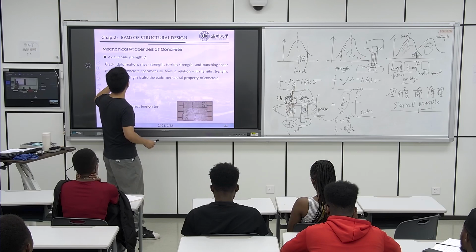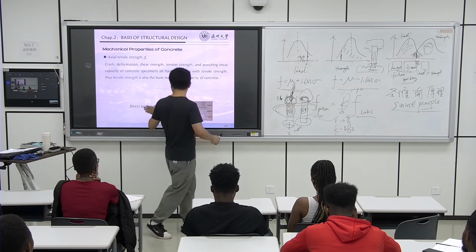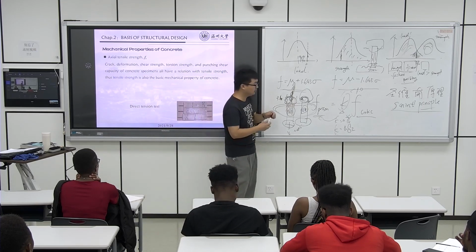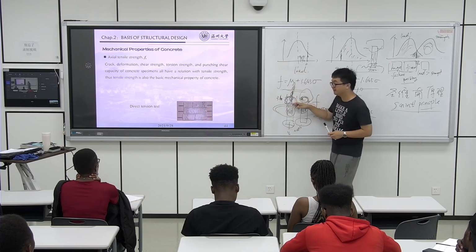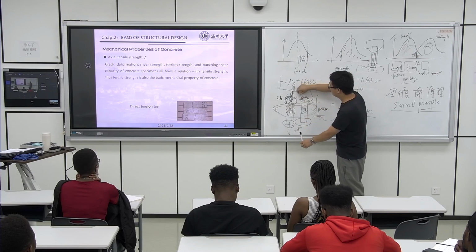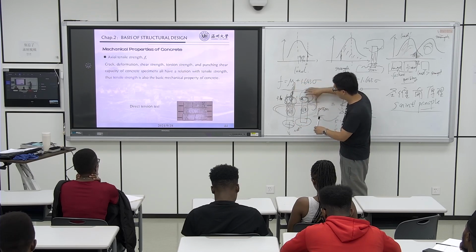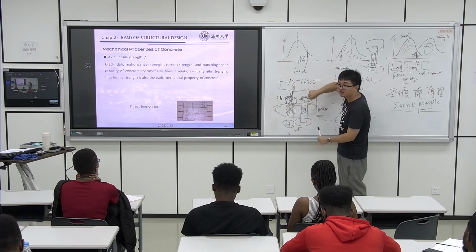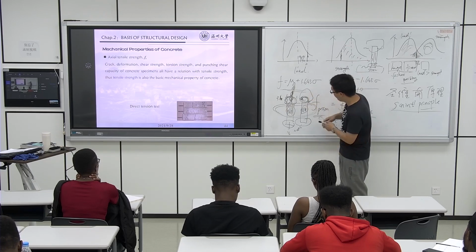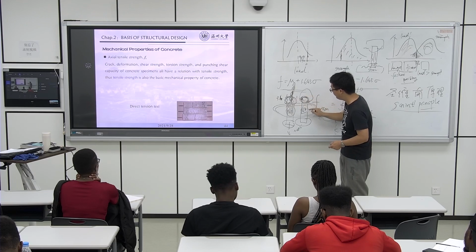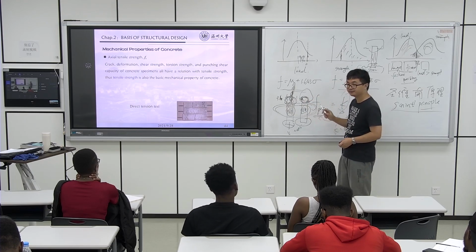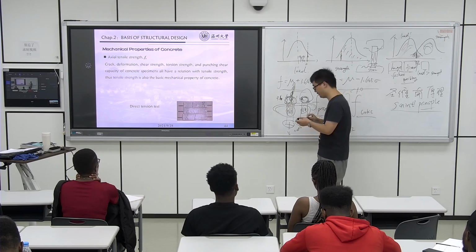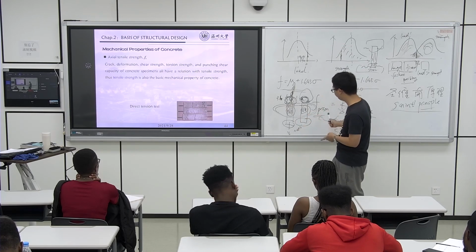For this tension test, the direct tension test, I want to show that we use steel bars embedded in the specimen to give the tension directly. They only affect the ends, where things will be different, and in the middle part they are the same. Saint-Venant principle.